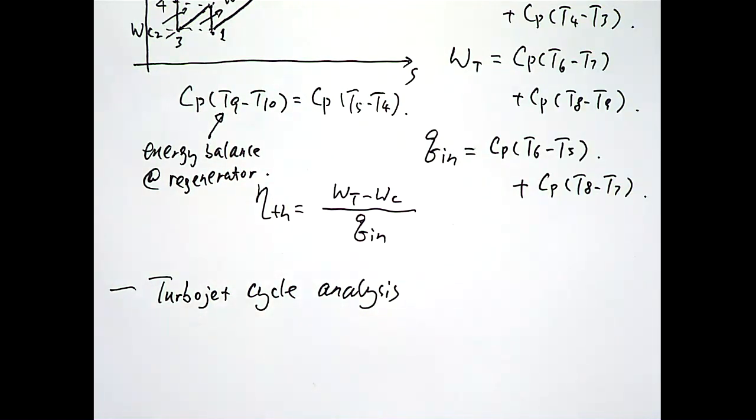And you can consider that's actually an extreme case relative to the Brayton cycle, because this cycle has all its output as the thrust. So it outputs zero shaft work. All the enthalpy in the process is being used to produce the thrust for the aircraft propulsion.